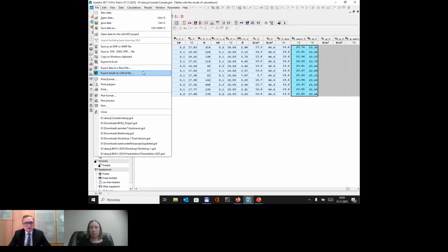And generally, lower delta T means a higher flow and also a bit higher power. So generally, we work with a pretty low temperature drop for the surface system, much lower than in case of a convective heating system.